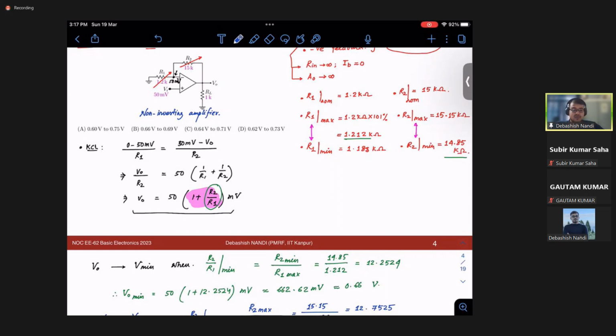These have some color bands, and based on the last two bands you find out the tolerance. If it is mentioned that there is 1% tolerance, the resistance value will not be fixed actually. It will vary over a certain limit. So you will get to know how your output voltage will vary, and accordingly you will design the next stages of the circuit. This is why this kind of analysis is important.